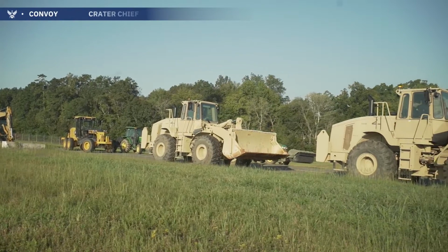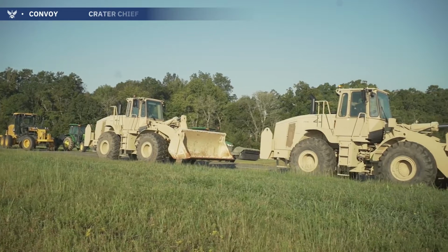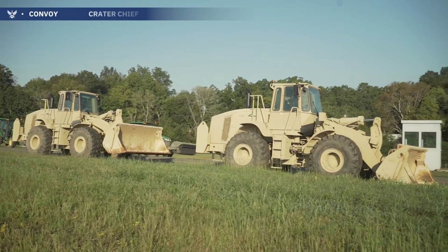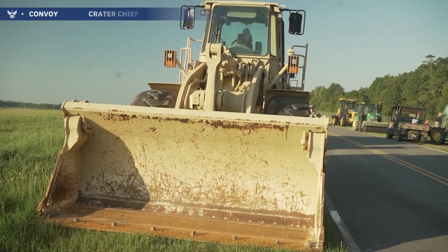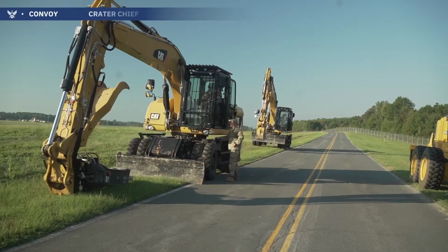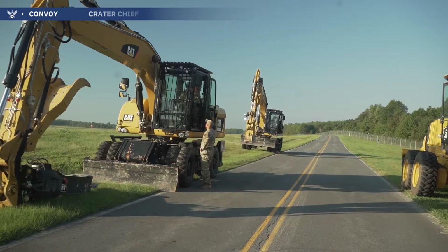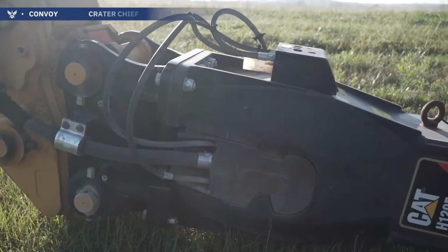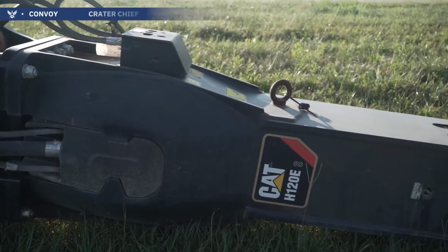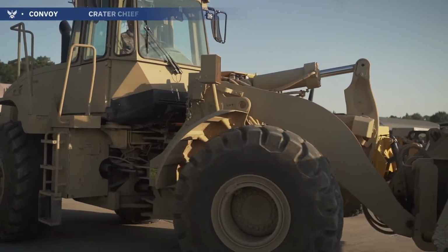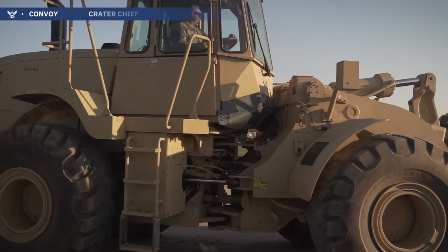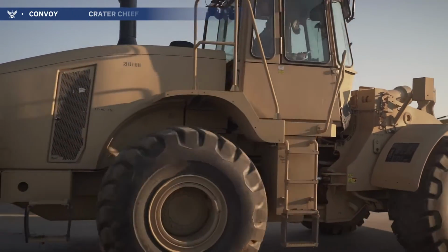When traveling to the repair sites, haul route clearance is the priority of the crater repair operation. All front-end loader and grader operators should assist by traveling to the crater site with buckets and blades down in areas where debris is present. Where the debris is heavy, front-end loaders should move debris to the side of the haul route, trying not to leave a thick, compacted layer, which could be too deep for graders to remove.